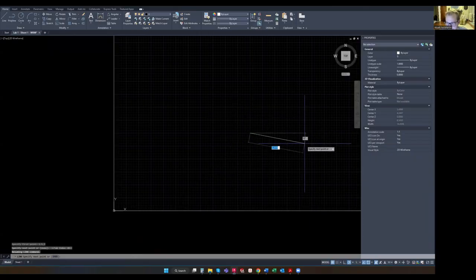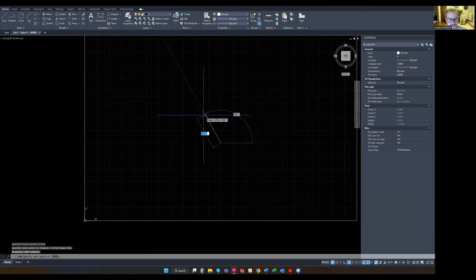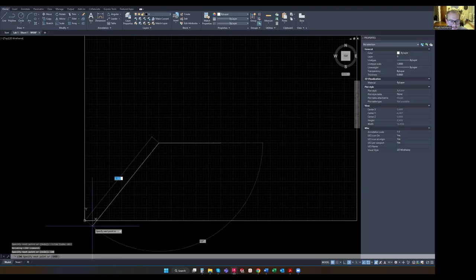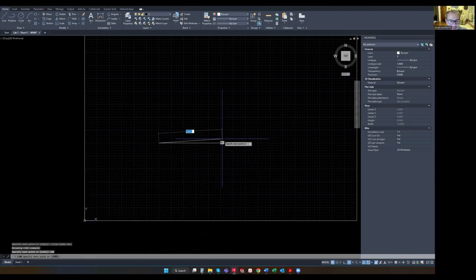Now, the next thing we're going to do is a distance and bearing. So we're going to say 2.5. So that's what we're going to type in. You don't have to click anything yet. Type 2.5, tab, 180. What that's saying is, it's looking at this point right here, the point where we start our line at 5.5, 3 on the coordinate plane, and it's saying, draw a 2.5 inch line at 180 degrees from this point. So this is now the relative 0 in a new coordinate plane.